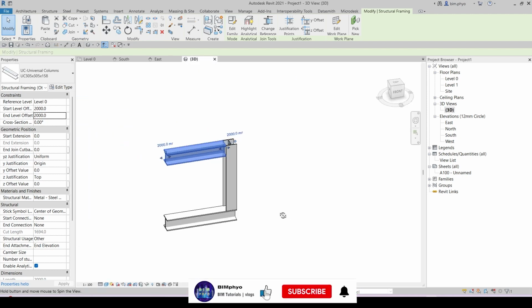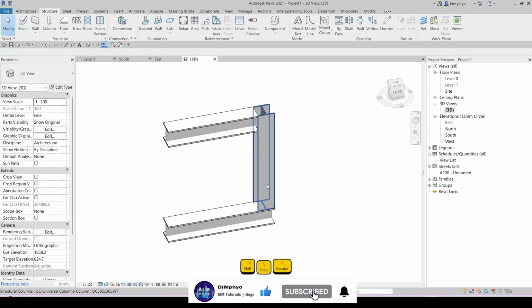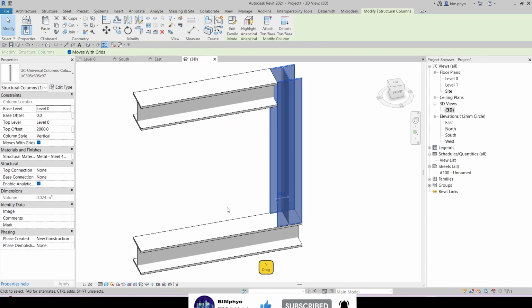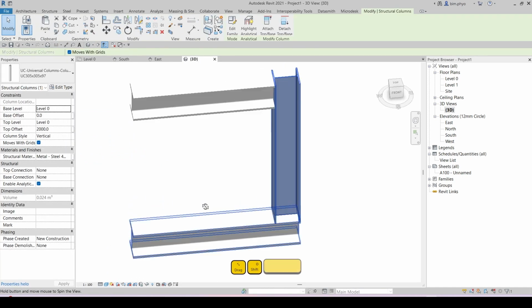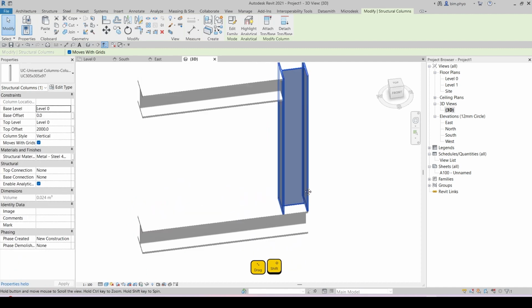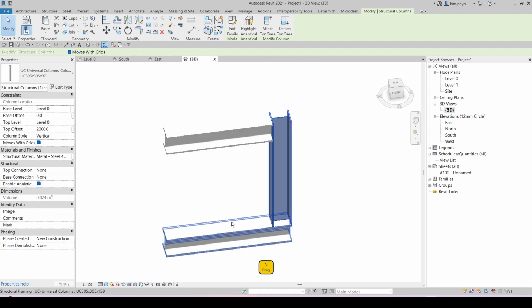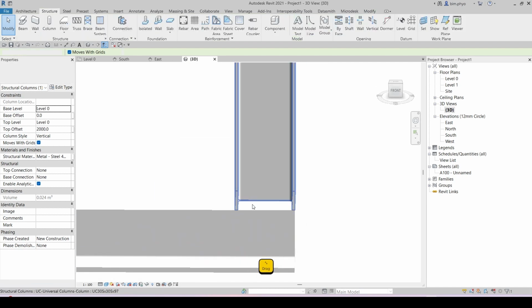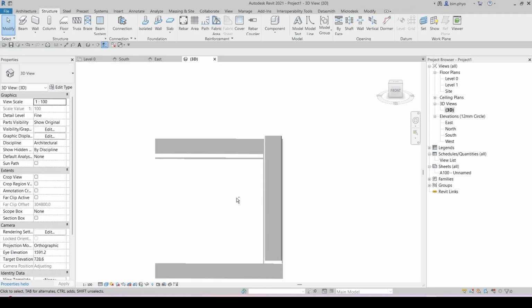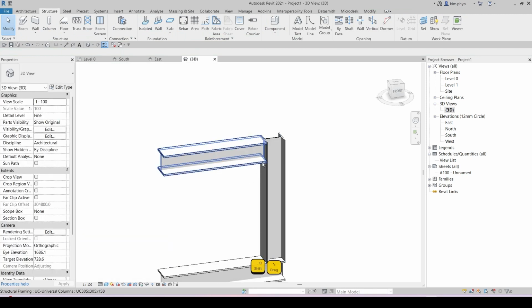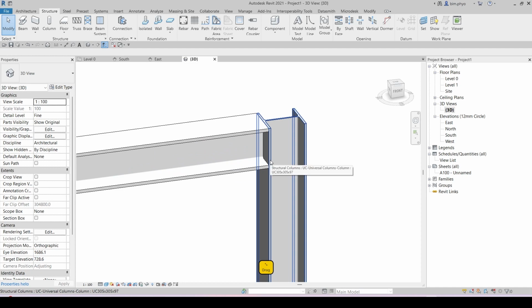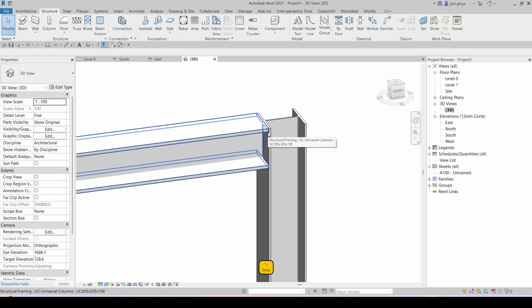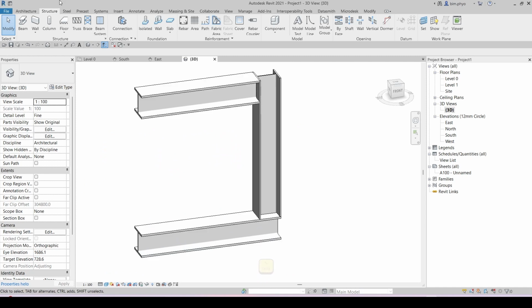So we're going to see it in the 3D view, but I might need this surface from this view. So the left side, I will rotate it. You press shift, then the structure column will rotate. So if we have it, I might need the structure plate in here and the structure plate in here. So how am I going to connect it with the plate, both plates, to the column and the structure framing? So how you can see on site, I'm going to create the plate.